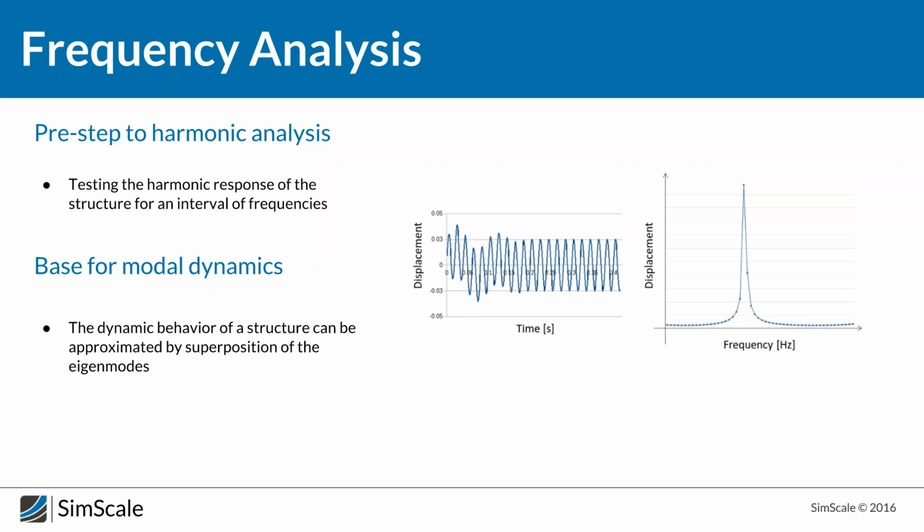So let's say we have an engine that starts up and we know this engine would work perfectly fine once it's at its working frequency, but when we want to start it, we have to make sure that the basement or the bearing of this engine does not have any problems within this frequency band. There might be that it starts vibrating heavily and we have a breakage here. Or we might have, for example, in a car, when we open up the top window, that via the wind that gets into the car, the car trunk simply starts vibrating. That is very annoying for the driver, and that's why we have to prevent that behavior.